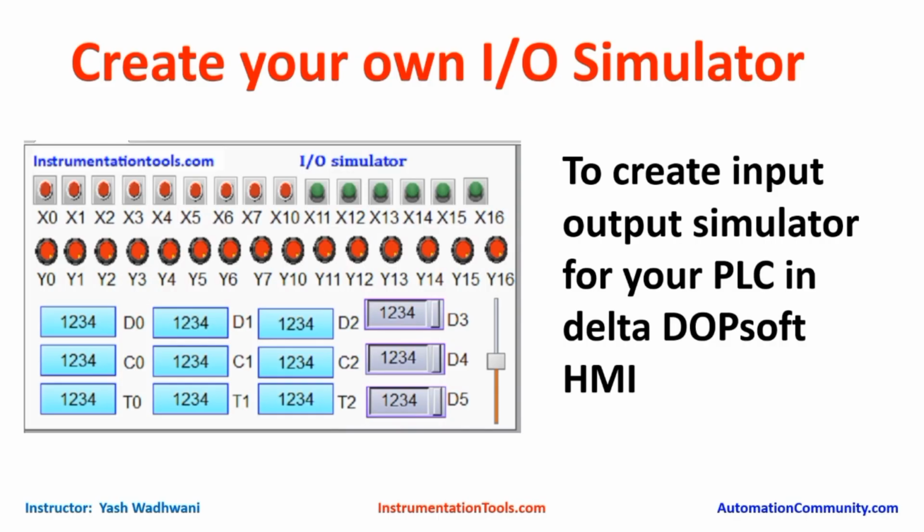Today we will see how to use DopSoft HMI software, and by using that software, how you can create an interesting input-output simulator for yourself. Now you would be thinking, what is the use of this? So the answer is, while learning PLC programming, you would be practicing so many examples. So just by using this screen, you can simulate any programming examples.